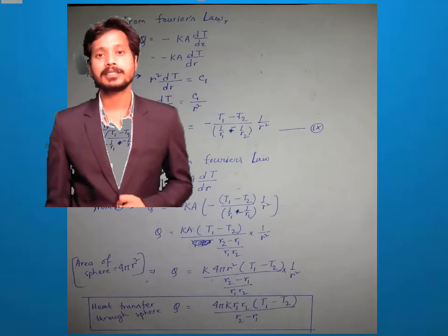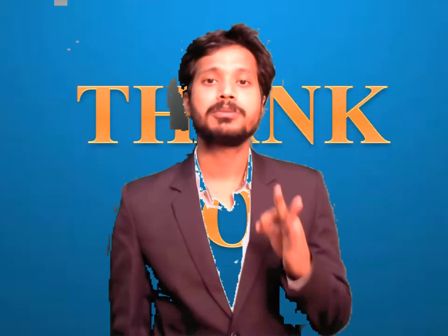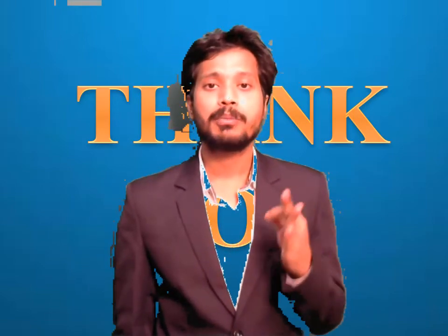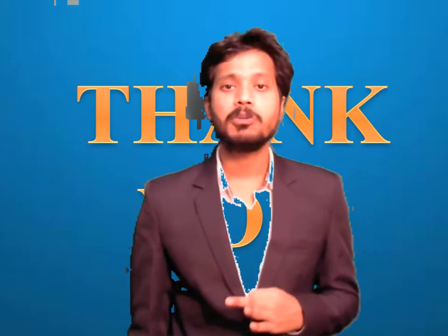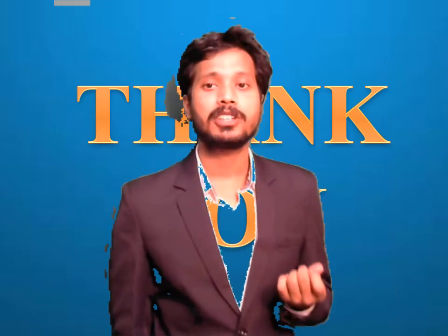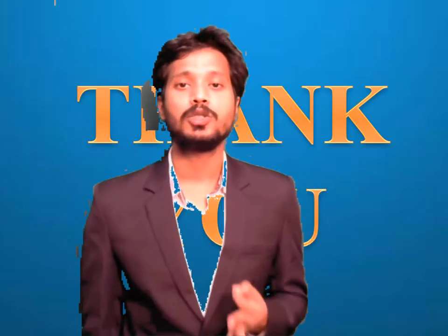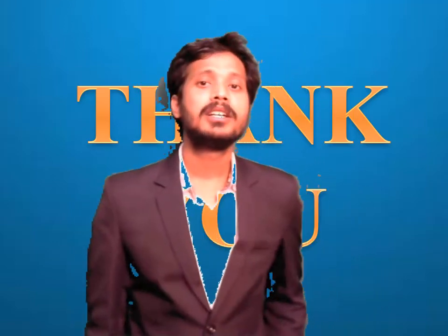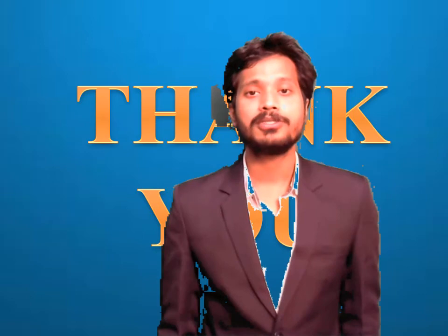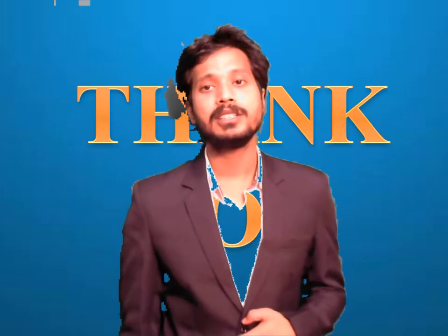Before ending the class, I'd like to revise today's class. Today we discussed the heat transfer of a spherical body, and the formula of heat transfer we get here is Q equals 4 pi K R1 R2 into (T1 minus T2) by (R2 minus R1). In the same way, the formula of heat transfer for a slab is Q equals K into A into (T1 minus T2) by L, and for a cylinder, Q equals 2 pi K L (T1 minus T2) by ln of R2 by R1. These three heat transfer formulas you must remember for solving numericals in your next classes.